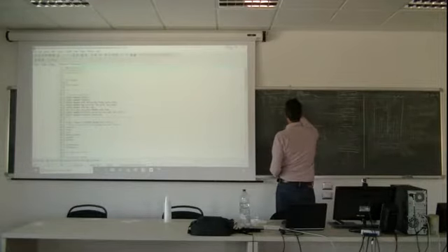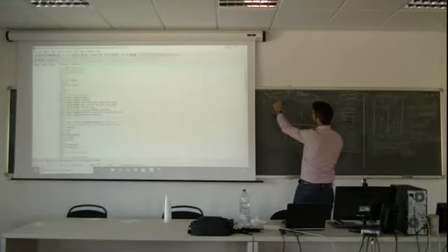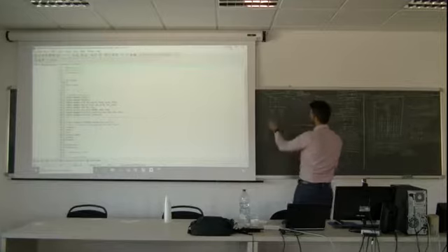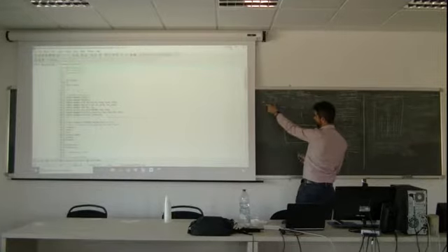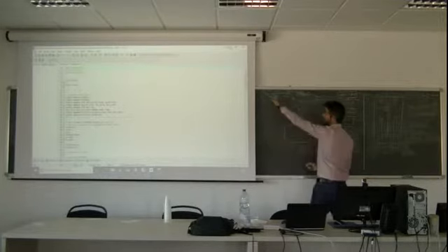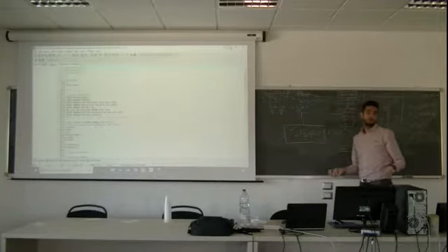Fourier here, minus k, forward minus backward, TP minus T west, divided by the distance between the nodes, multiplied by surface. Surface, in this case, it's the same, right?